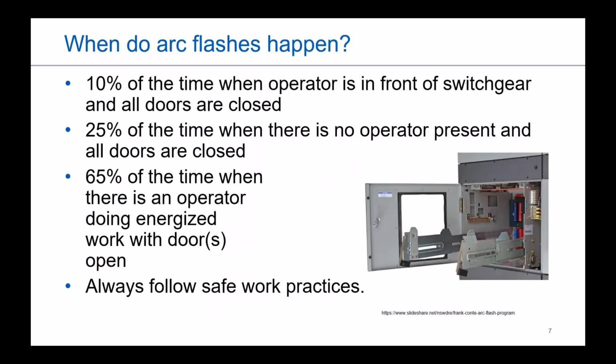And so when you look at when they happen, 10% of the time, it's when an operator is in front of switchgear or an enclosure and everything's sealed up. A quarter of the time, it's when there's no operator present at all, doors are all closed, but most of the time it's when someone is physically in front of the equipment doing energized work with doors open.